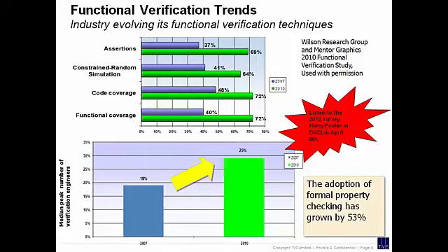Constrained random as well. We'll talk about constrained random simulation on the next slide. Code coverage. Did we do code coverage? I think code coverage is probably mandated, yeah? For certain safety levels, you'd probably get code coverage mandated. Maybe statement, sometimes branch, MCDC as well. So you get MCDC mandated for you. You have to do that. And functional coverage as well, we'll talk about.